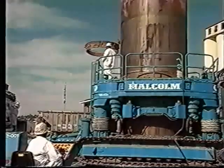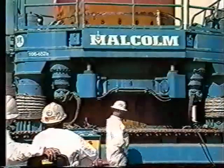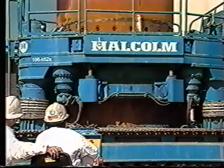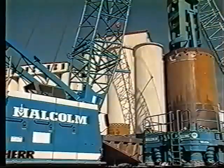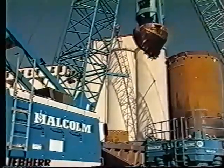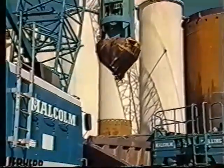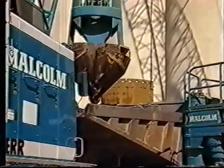The bridge support was designed with 2 drilled shaft-supported abutments, with 4 6.5-foot drilled shafts at each abutment and 7 piers with 2 10-foot shafts at each pier. The geotechnical makeup of the site for the installation of the shafts was mainly loose to medium dense dark gray to black sand. The grabs clam out the dirt and muck, while the rotator continues to rotate, forcefully twisting the casing into the ground.